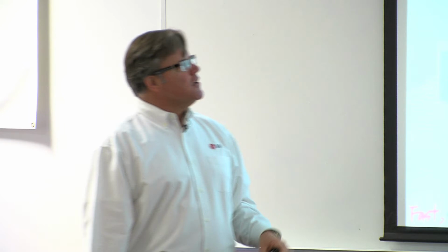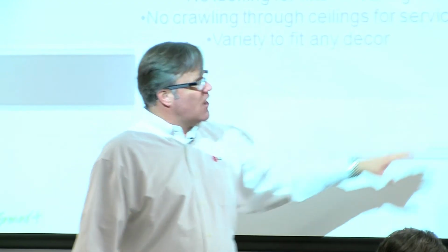So, pieces and parts that you have to deal with. We've got a couple of different criteria. Number one, we can do ductless, and all that means is there's no ductwork involved. The only thing running to these things is refrigerant pipe, and so these things will sit in the space. This is a traditional 3-foot long, hangs-on-the-wall mini split style, but there's lots of different styles.